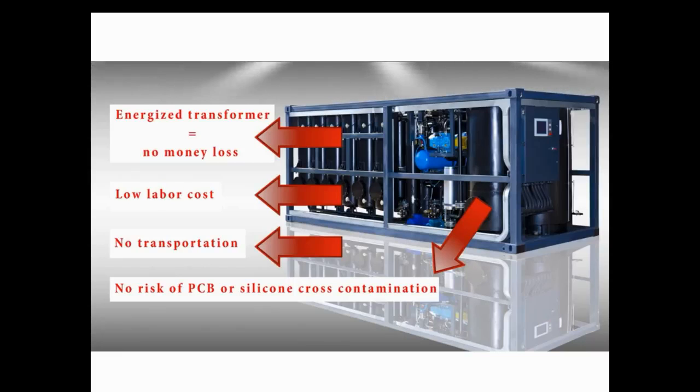Until now, we have been speaking only about technology advantages, but there are disadvantages as well. Therefore, there is not sufficient mobile equipment available. Think of all the transformers in your area. They might be thousands. Taking into consideration that you should do oil regeneration every 10 years, you will not cover the whole network before you should do your very first transformer again.